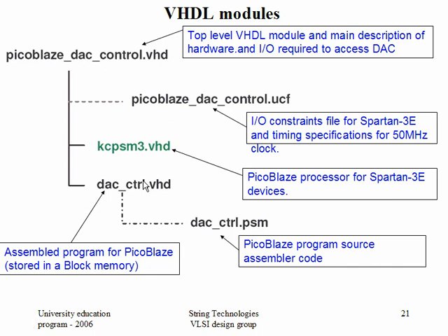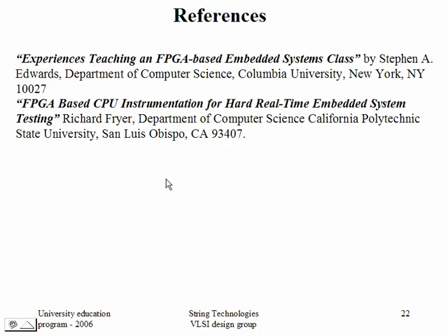It will have an external ROM or RAM from where you fetch the instructions and keep executing. In a similar way, here also my soft processor core will keep fetching and executing the instructions. That machine code is coming from where? It comes when you assemble your assembly code: you get a VHDL file, and that VHDL file will have it. I'll show all these things on Monday.